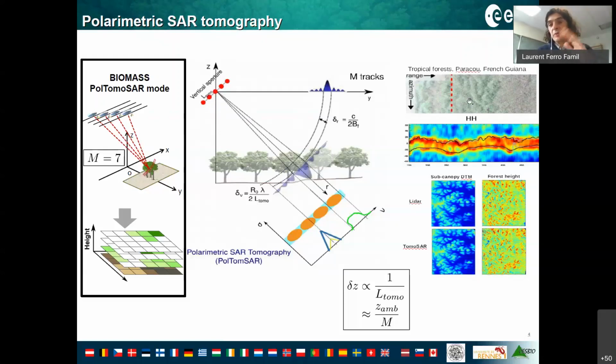Because when the range slope varies, you have huge variations of reflectivity. So it's very hard to infer tree height or biomass content using only one image. People aim to do this, but you need to do a lot of compensation. You need to know the topography of the scene. Instead, if you just combine 6 images in a specific configuration, the multi-baseline interferometric configuration, and if you